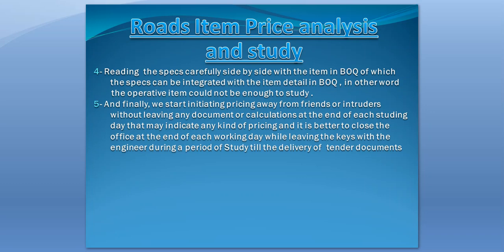We must read the specs carefully, side by side with the item in the BOQ, as the specs can be integrated with the item details in the BOQ. In other words, the operative item alone could not be enough to study.